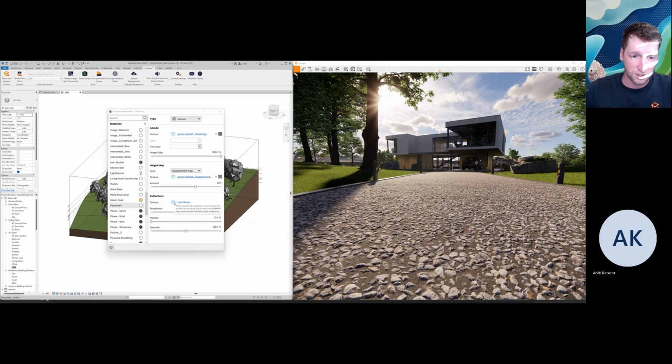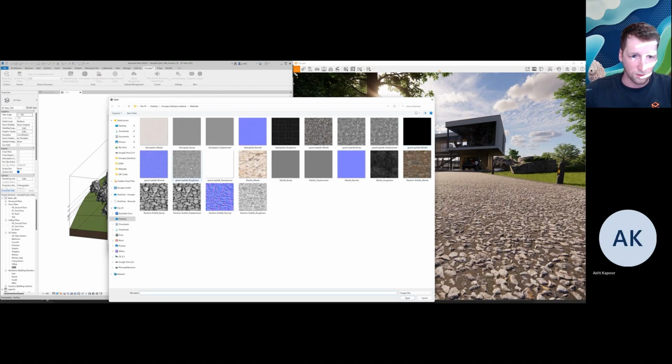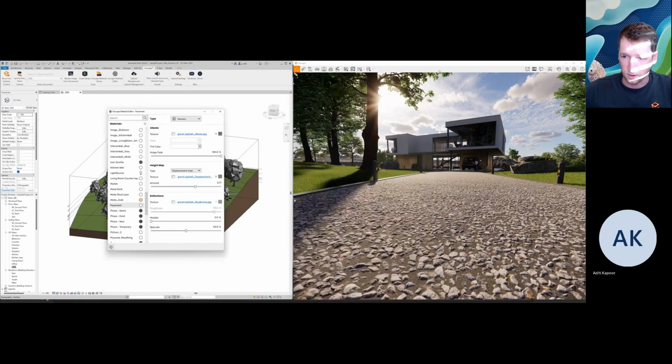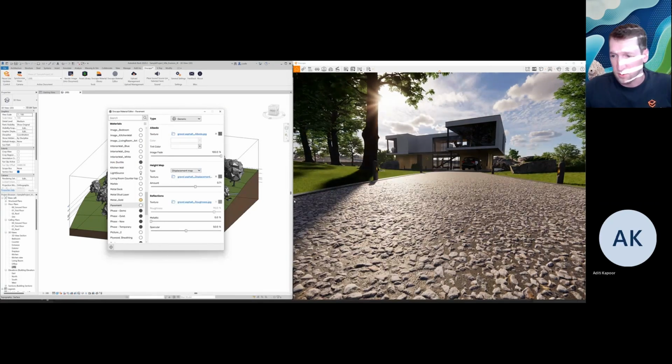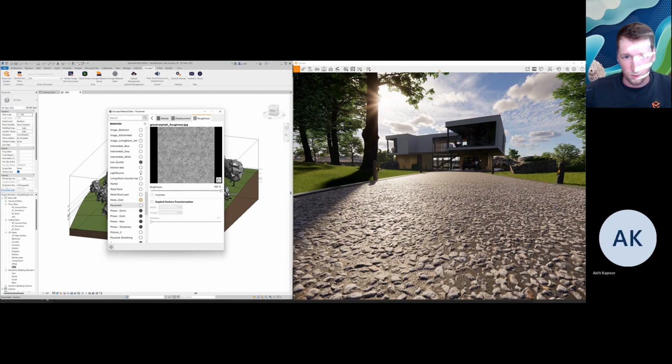And the last map that we'll add in is that roughness map. So I'll just click where it says reflections and click for the roughness map. I'll click open, and then we can see here too, this material is not really super shiny, but we'll still be able to see wherever the difference is in reflection values as well. Again, wherever is darker is going to be more shiny and reflective. Wherever is lighter, towards the white area, is going to be dull.